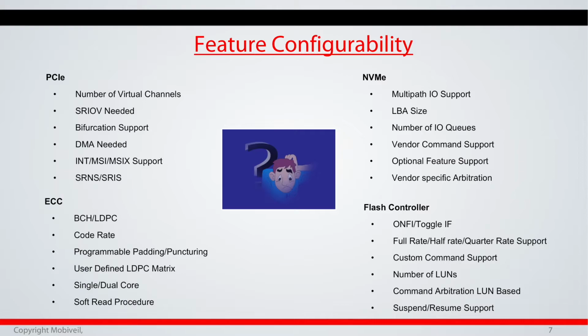For example, if you look at the PCI Express, whether the design can support multiple virtual channels. Is SR-IOV supported or not? Because PCI Express, you may want to have an SR-IOV solution. Bifurcation, can the controller itself be supported in a bifurcation mode?